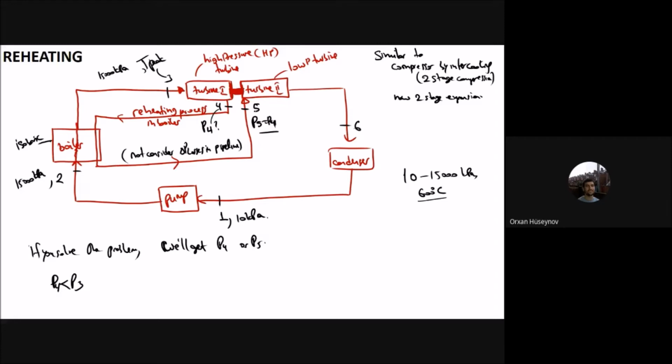And then you have P5, which is the inlet of turbine 2, and from that inlet of turbine 2, the pressure again drops to P6. And since it is the condenser, and this one is also isobaric, 6 should be the same as 1. They should have the same pressure because it is isobaric. Therefore, it is also 10 kilopascal. Okay, so this is the general chart here.